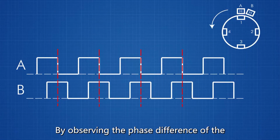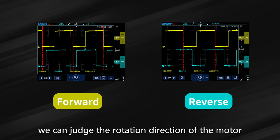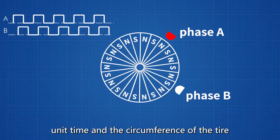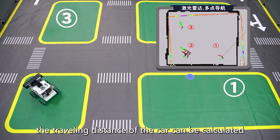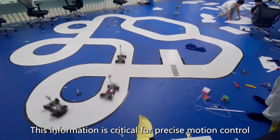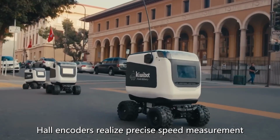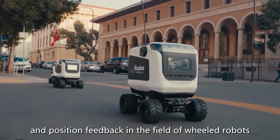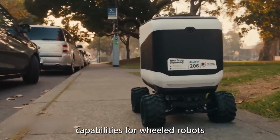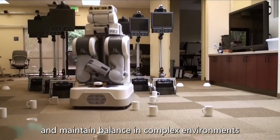By observing the phase difference of the two sets of signals output by the Hall encoder, we can judge the rotation direction of the motor. According to the number of signal pulses per unit time and the circumference of the tire, the traveling distance of the car can be calculated, and the motor speed can be monitored in real time. This information is critical for precise motion control, path planning, and attitude adjustment. Hall encoders realize precise speed measurement and position feedback in the field of wheeled robots, providing accurate motion control and positioning capabilities for wheeled robots, enabling them to avoid obstacles and maintain balance in complex environments.